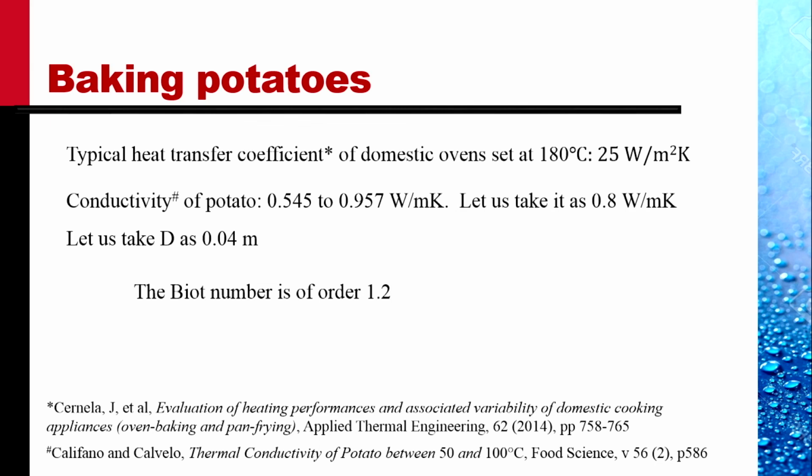Let's take it as 0.8, a typical value. And let's take the diameter of the potato to be 4 centimeters, a rather small potato. Then the Biot number is of order 1.2. The Biot number is order 1.